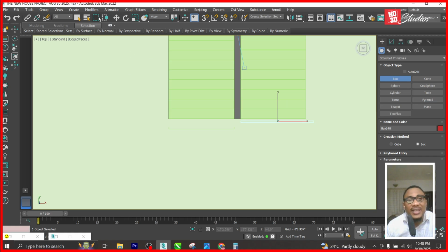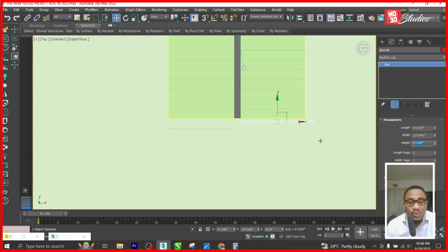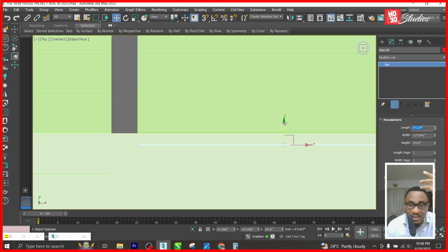Let's give it a height of 3.5. I think a height of 42, sorry, 3.5. That's 42 inches. So in some parts of America, they recommend balustrades of such height. Then the length, it can be a glass balustrade. Let's say the thickness can be 0.02, 10 mm glass.